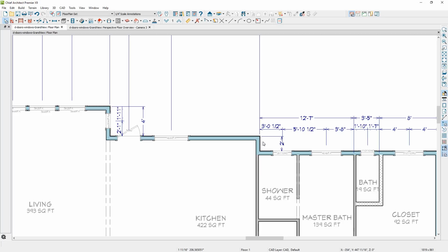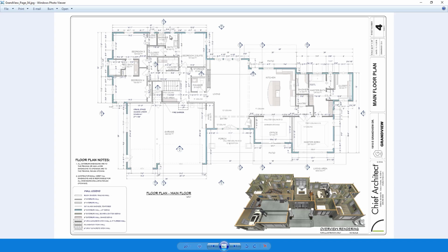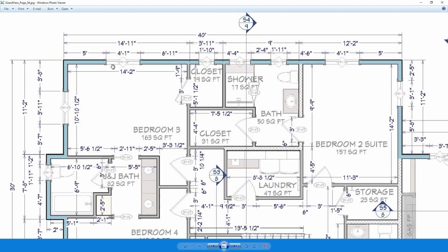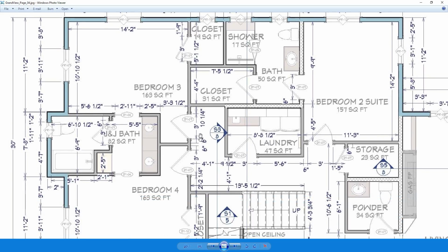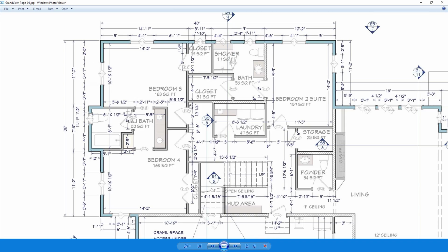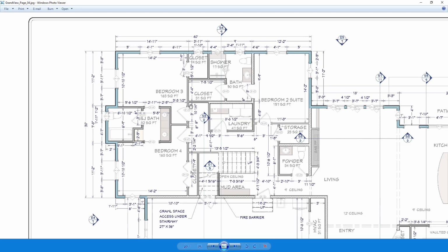If you take a look at my completed floor plan here, I ended up dimensioning to the frame of the window, and you can see the way that I ended up cleaning up that dimension in this way. Sometimes I like to know where the casing is. In particular, if you go to the interior of the room, I like to know how much space I have for my casing or my door frame into the wall. But I think most people like to use centers, so that's the way I wanted to show you how to set up your dimensions to go to the center of that object.